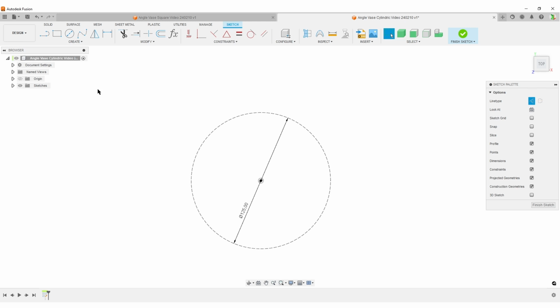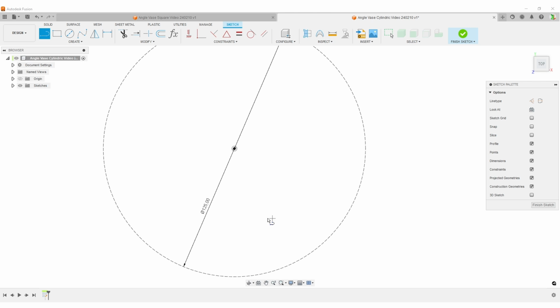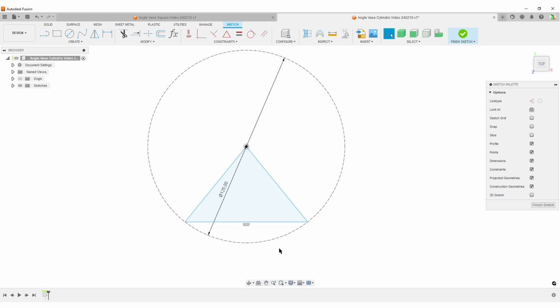So let's do this. We're going to do some lines to help us. Turn off construction line. So I'm going to draw a pie part here. I'm going to go over here. Going to go here. Make sure I get the horizontal constraint here. Hit the line over here. Go up here. So this is like a pie section. I'm using escape to turn off the line feature. I'm going to move it slightly out of the way. So this is going to be one section.